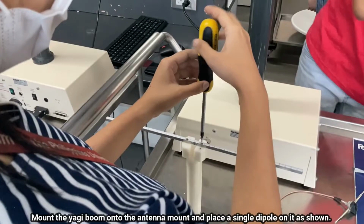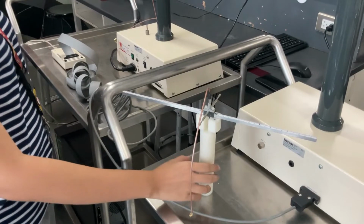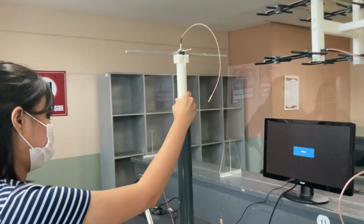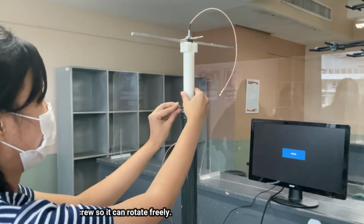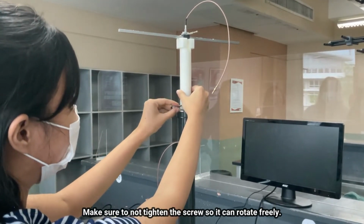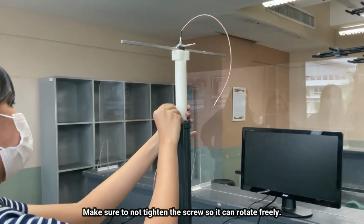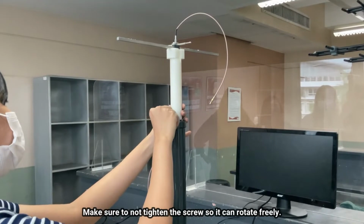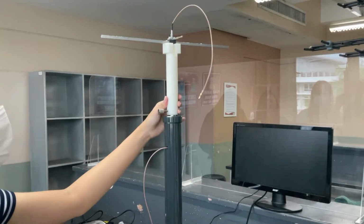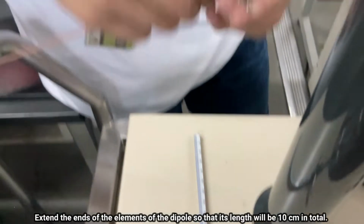Mount the Yagi boom onto the antenna mount and place a single dipole on it as shown. Make sure to not tighten the screw so it can rotate freely. Extend the ends of the elements of the dipole so that its length will be 10 cm in total.